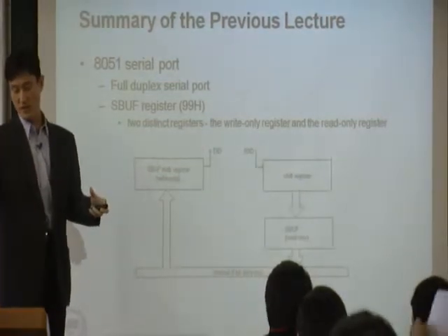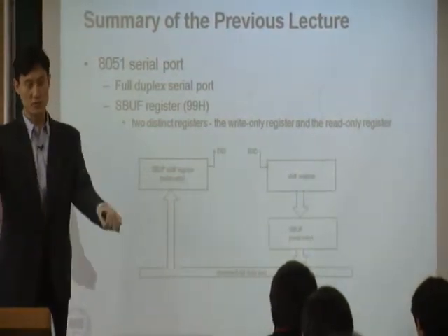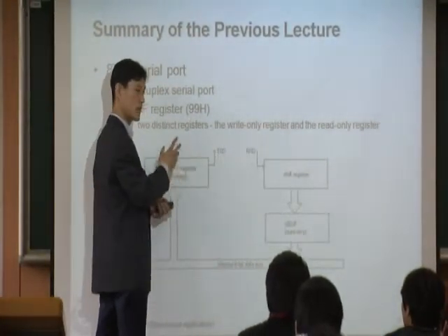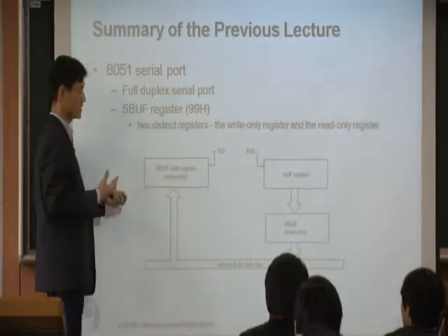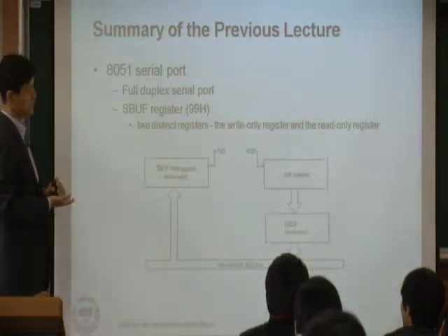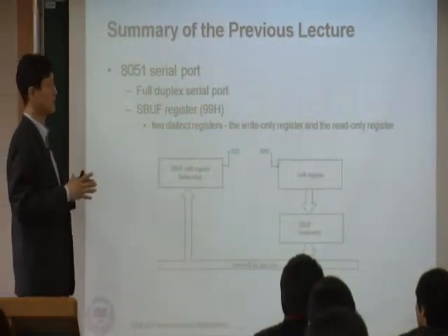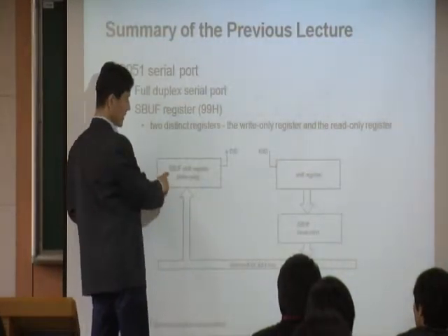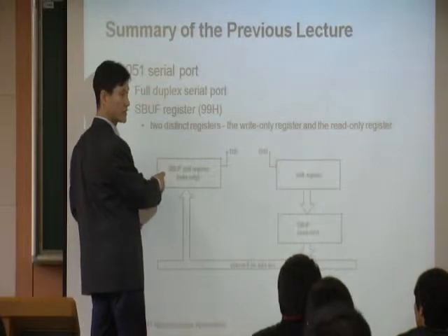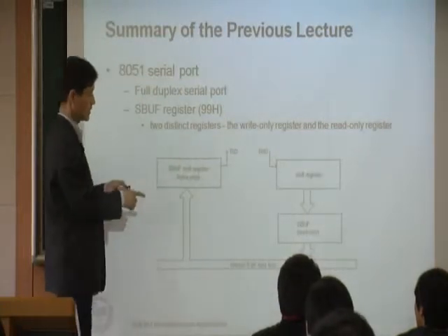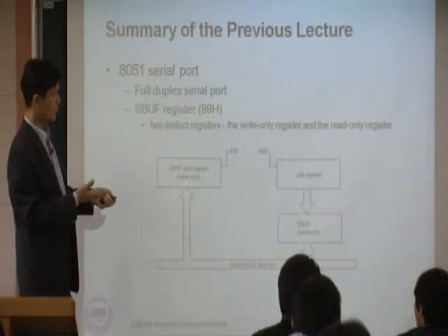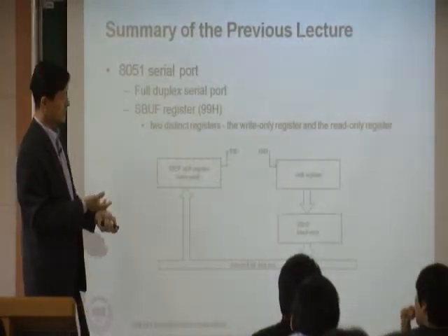You have an 8051 board. We have a PC right there. So you connect like a USB connection. And using the RxD and TxD pins in 8051, we want to do serial communications. And this picture shows you what happened in the hardware of 8051 processor. As you remember, we have a register called SBUF.